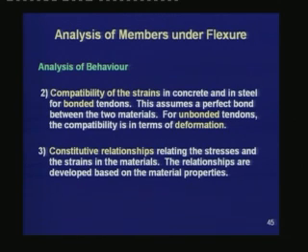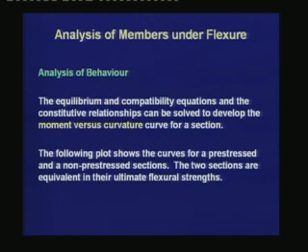The third principle that we use is the constitutive relationships relating the stresses and strains in the materials. These relationships are developed based on the material properties. The equilibrium and compatibility equations and the constitutive relationships can be solved to develop the moment versus curvature curve for a section.